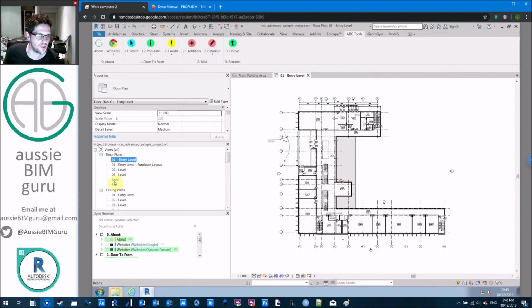So it's just all about how you build the script. You can see that now in all my views, floor has been replaced with level. So super powerful. There's so much potential for what you can do with this. I really hope it works in Revit 2020. I haven't been able to test it or hear from the company, but this has such a bright future in not needing people to use C# or Python in order to package their scripts into a deployable toolbar. You can imagine if this is on a server location and you configure everyone's copy of Dynamo to read the same location and they have the same custom packages, you can essentially package the toolbar the same way. It's very, very powerful.